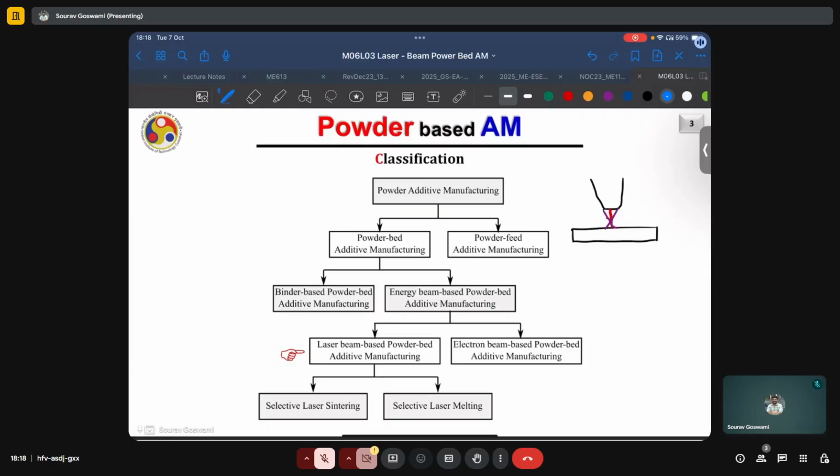What we also saw is the efficiency or mass deposition efficiency in this case is limited by certain considerations, primarily because of the very high momentum that these particles bring and that they can bounce off, so there can be powder spatter. Then there is the catchment efficiency, which is the mass of powder particles that actually goes into building the bead over the total mass of powder which was fed to the system.